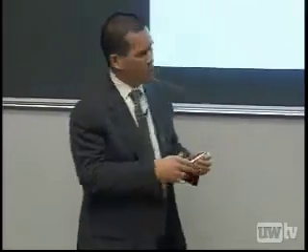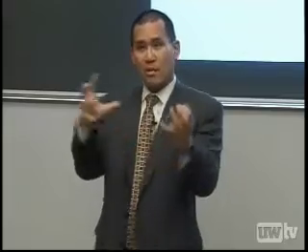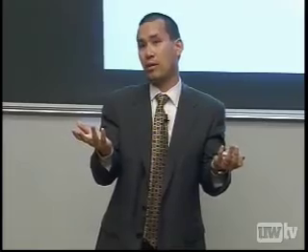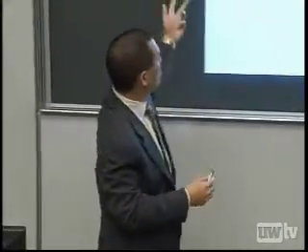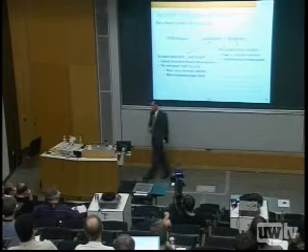Caches are interesting. If I think about putting more cores in a chip, I need proportionately more memory than cores. If you think about it, if I take more cores, put them on a chip, and each core has the same amount of memory as it used to have, its miss rate is the same, which means the total number of misses for that larger block is going to grow with the number of cores, and that's going to swamp my chip bandwidth. Okay, so I need more stuff. I need more cores. I need disproportionately more memories. I need more switches. I need bigger chips.